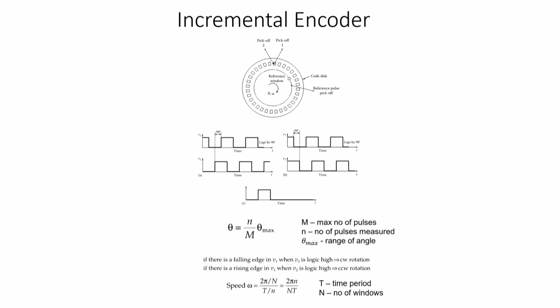If you only look at one part of an incremental encoder, just one level of these arrays, we can call these pick off points 1, 2, etc. You can measure, for example, from this pulse to this pulse, what degree of shift has happened, and at different angular velocities you expect these to come up at a particular rate, which you already know.